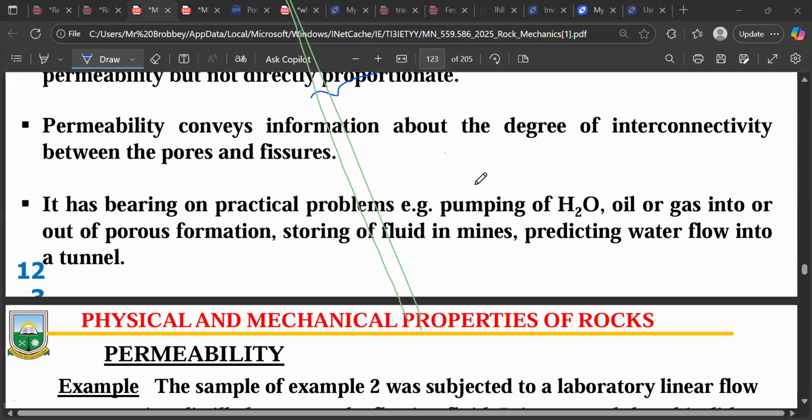And now you drill the place and then you have water in your holes. You didn't plan for emulsion or explosives that can work over there. Then you would have to drain or dewater the blast holes, and that is causing extra time and money and others.